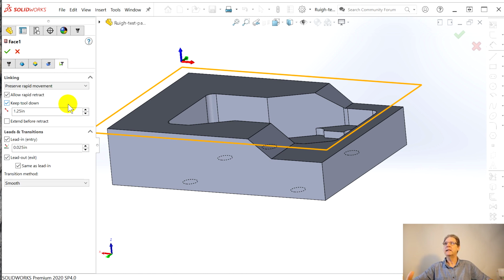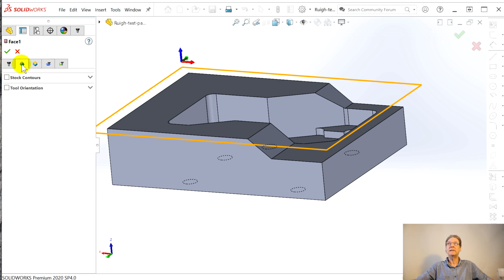And then here the linking, and what I love about this, unlike SolidCAM, when you do a new operation, it just inherits the tool from the last, which is the way everyone on earth wants to work. The SolidCAM is just two clicks, click, click, and you pick the previous tool. But it's really nice that they inherit. So you hardly ever, like in this part, that's going to be a 1/4 inch end mill through the whole part. You're hardly ever clicking here, and you're hardly ever clicking here. So now there's just 3 tabs to worry about.